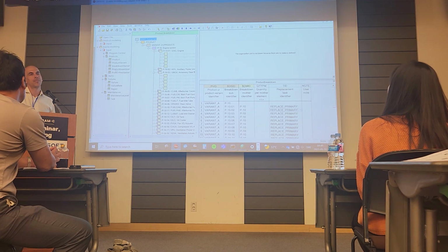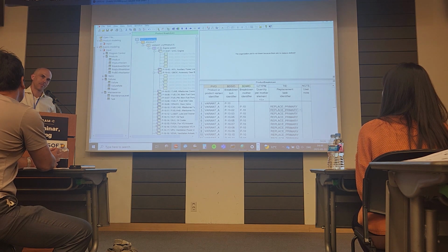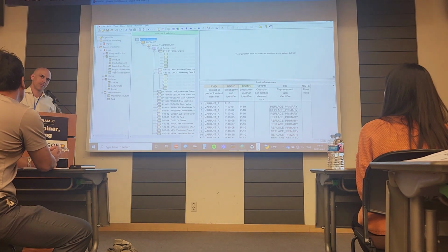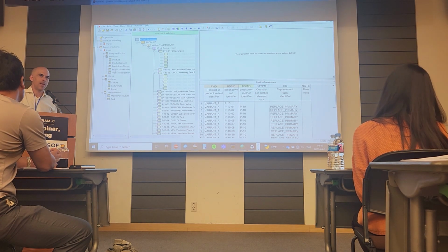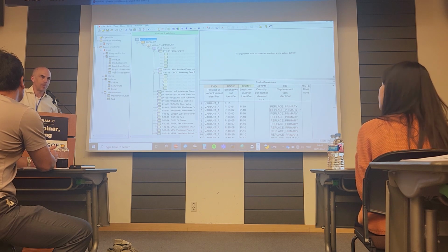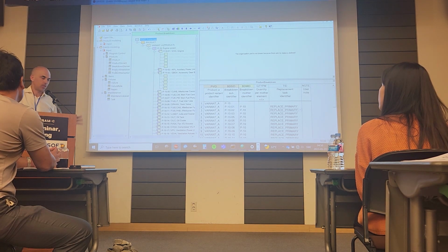Another question was the slide. Could you show at the very first, like there is MTBM and MTBF. So when I put the failure rate in this program, should I put MTBM and not MTBF? The MTBF. MTBM means mean time between maintenance, and that comprises the total of scheduled maintenance and unscheduled maintenance. But you're correct. With failure rate, it's MTBF.